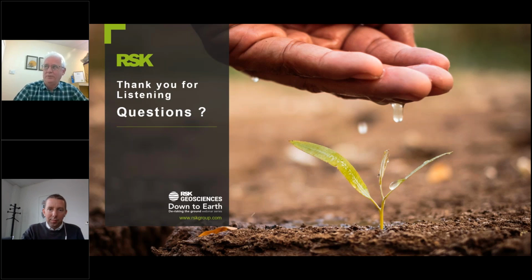So there will be guidance coming in, and as I hopefully articulated in that talk, I don't have the answer either currently. But people with access to all of the huge volumes of research data, I forget the figure now, but in my reading around for parts of this talk, it's a crazy amount of data. I think it's in the order of 60,000 test results in London Clay alone. So there's a huge library of data about the way in which the shrinkable clay soils have behaved so far, given different climatic changes annually.